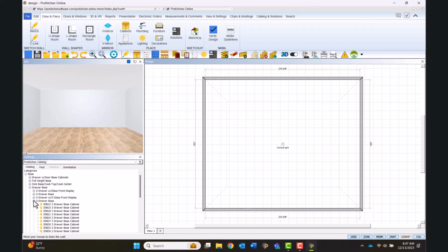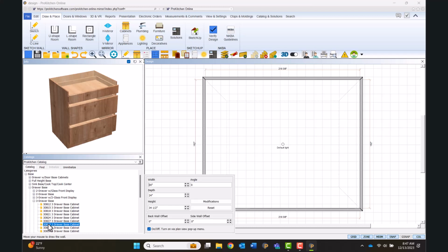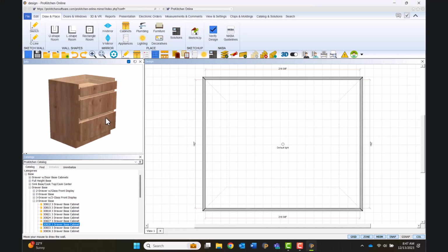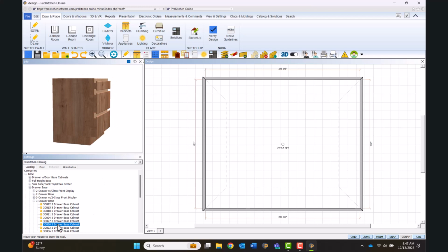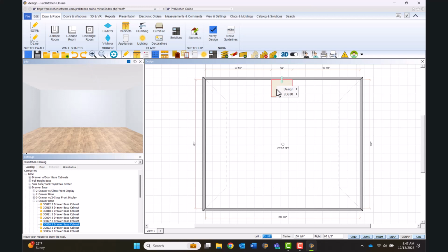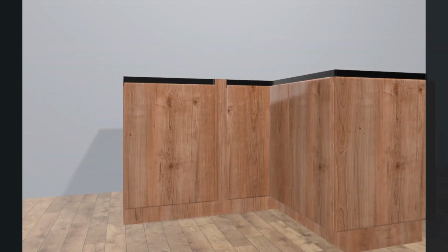When designing, you will notice that placed cabinets now have void spaces where the channels will be placed. Continue to design as usual, as it is easier to apply the channels after design completion. Also, when designing with channels in mind, be aware that if you are using fillers, it is important to know that manufacturers do not support application of channels to filler material, and the channel will not render across the fillers in the 3D rendering.